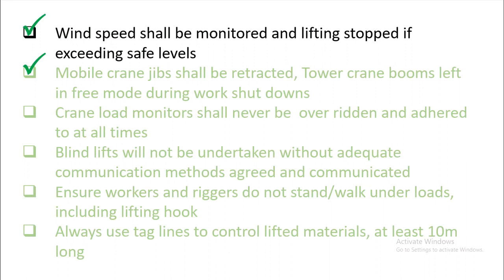Sorry, the unit is per hour. So when you are doing your lifting assessment, you need to include the wind speed at that time, and monitor the wind speed from time to time while the work is in progress.